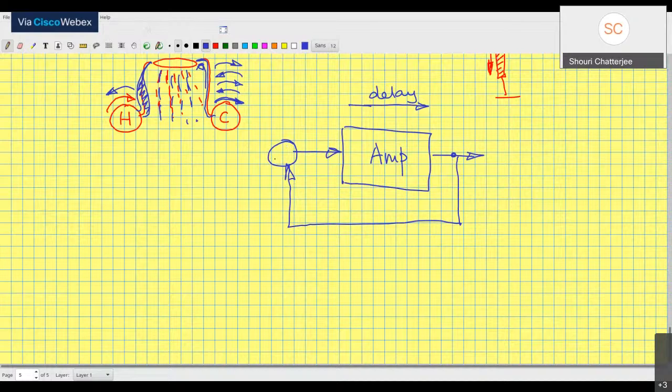So the problem comes only when you have this feedback, not when you have it open loop. For example, if I put an inanimate object inside the shower, it's fine. There is no problem. You hold it under the tap, it's done. Only when there is feedback, when I am feeling the temperature and trying to adjust for the right temperature, that is when the problem is.